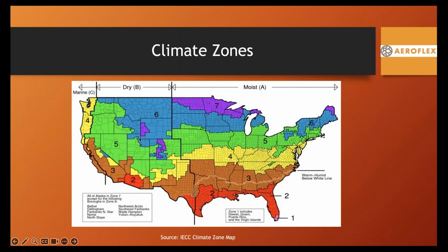What about energy codes by states? This comes into play. 90.1 and IECC are adopted not only by states, but also cities, towns, and other municipalities. The local jurisdiction or the most stringent requirement usually overrides the others.